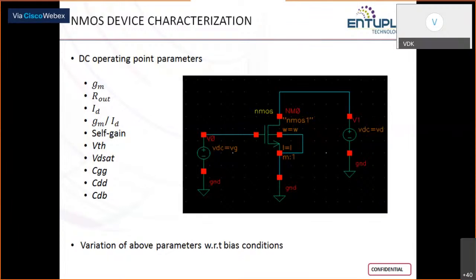We go the same way. We characterize the PMOS device also exactly the same way. We are again simulating the PMOS device for W equal to 5 micron, L equal to 0.18 micron. We would prefer to simulate it for more values of lengths, maybe at least another 3, 4. Once we do that, we are choosing L same as the NMOS device, and then we figure out the region in which we must operate the PMOS